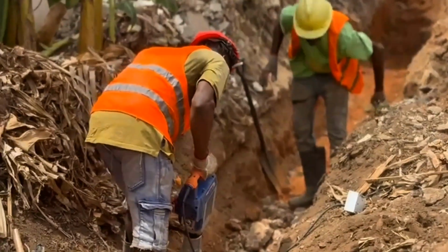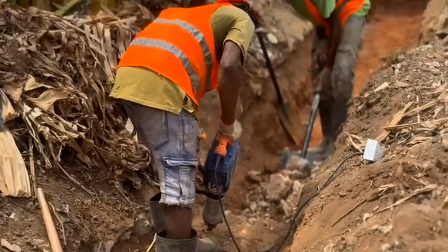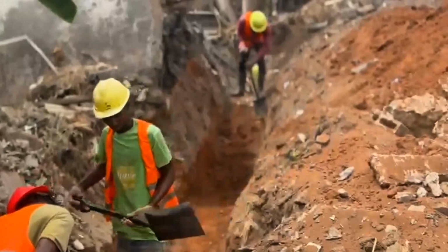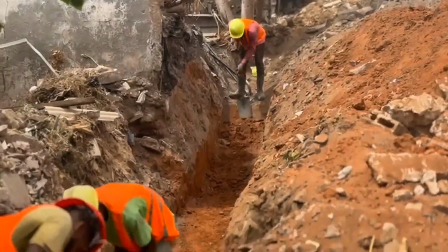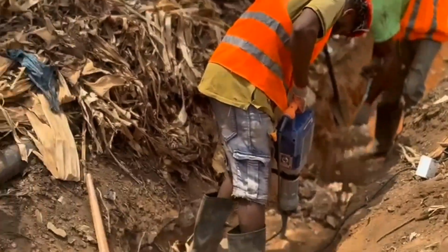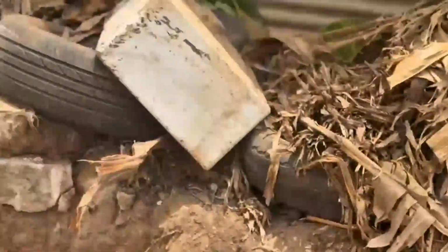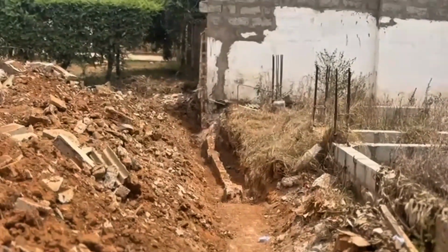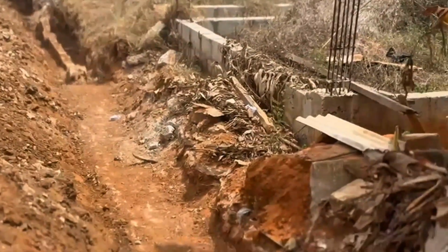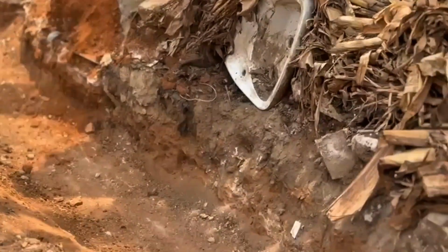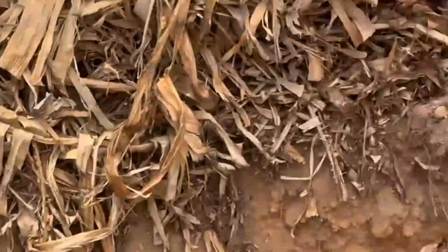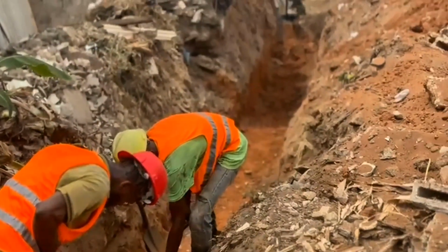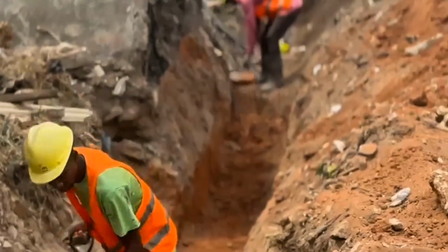And for this, from my experience, a laborer is supposed to excavate a cubic meter a day. That means a laborer is supposed to excavate 1 cubic meter a day. So knowing this, you can say that if one day is a cubic meter, it's going to take 25 days to just excavate this 25 cubic meters. That's just one laborer. But if you want it to go fast, you also get more hands. But definitely it's going to end up at this value, 3,750, because 150 times this 25 cubic meters is going to be the total cost for excavation. It doesn't matter if you take more hands, it's just going to make it faster if you use more people.